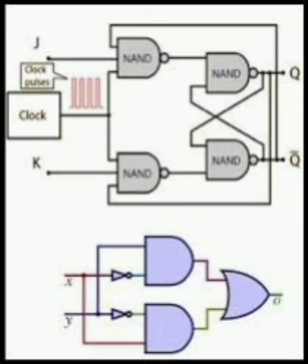In a parallel adder, n full adders, or n minus 1 full adders and 1 half adder, or 2n minus 1 half adders and n minus 1 OR gates are required to add two n-bit numbers. The total number of 2 to 1 mux required to implement a full subtractor is equal to 7.